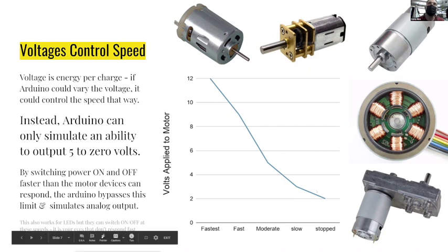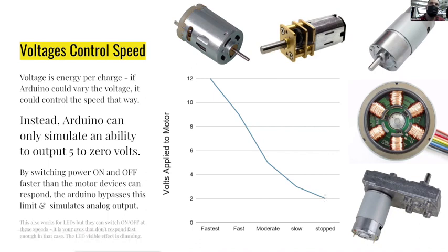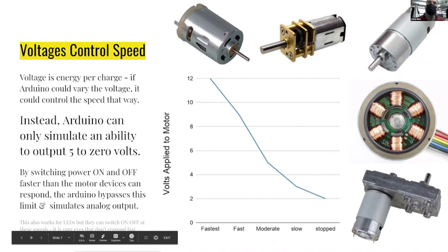But you've got all of this. You'll notice I stopped before I get to 0 on motors. Most of the time they have a certain minimum voltage they really need to do much of anything, and so they'll oftentimes stop if you give them too low of a voltage. It's good to have played around with the motor enough to know what your cutoff is for it to not work. But it's a neat thing.